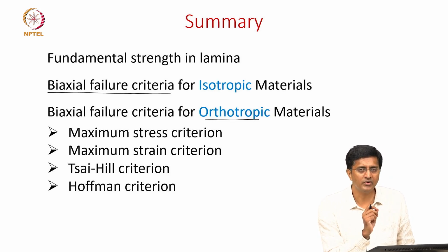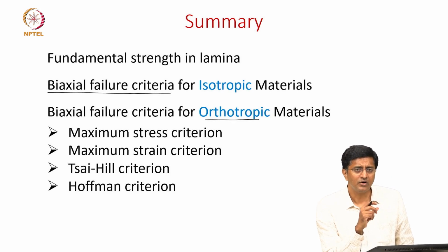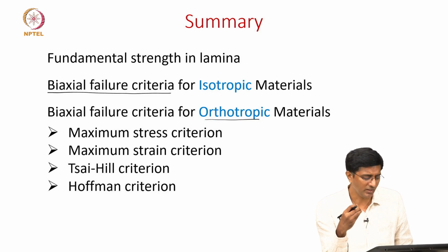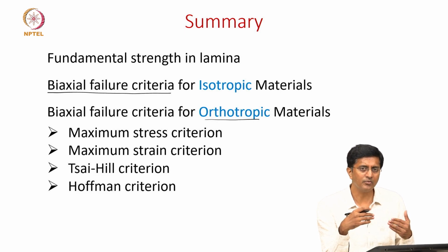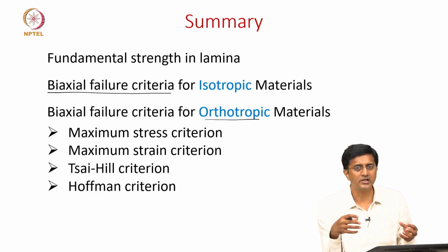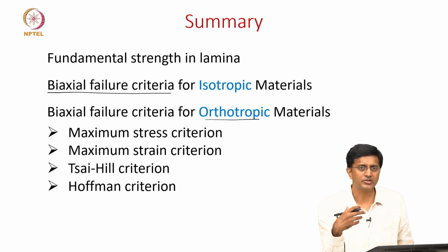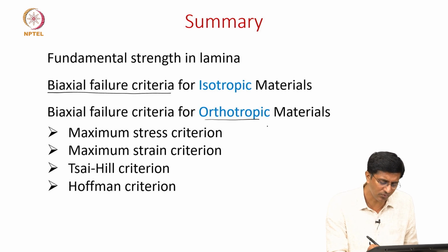One, we said we cannot go with the failure theories. The reason is failure theories are based on failure mechanisms, trying to come up with an analytical expression based on the failure mechanism. But in composites, since there are several failure mechanisms which are competing with each other, coming up with a theory whose derivations are based on these failure mechanisms is difficult, mostly because several failure mechanisms are involved and things get complicated because of the complex stress-strain relations. So instead, we are focusing more on the failure criteria.